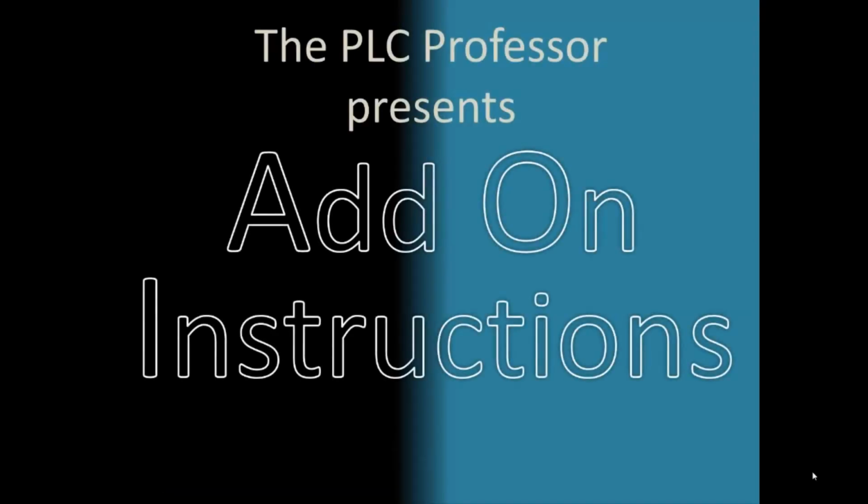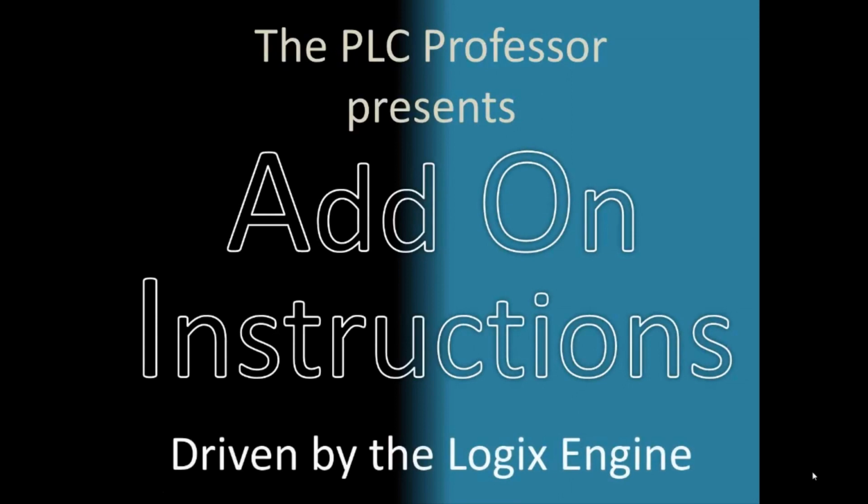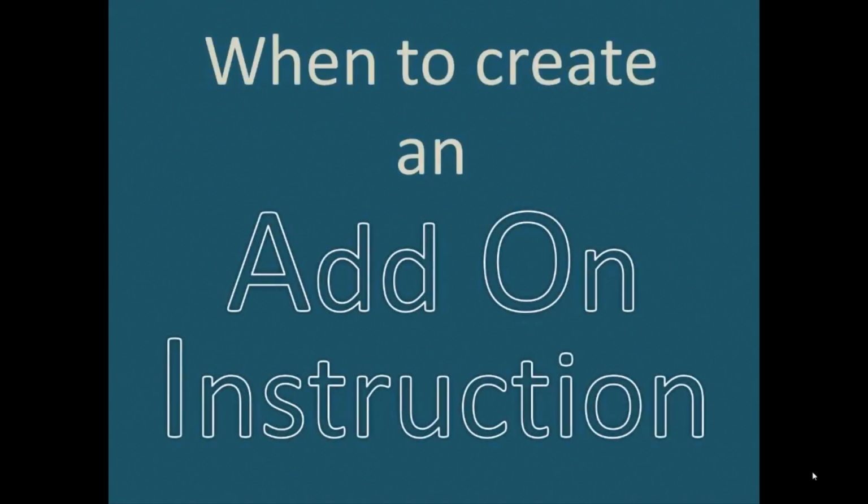The PLC Professor presents add-on instructions driven by the Logix engine. When to use an add-on instruction. When to create one. Complex instructions tend to be highly application specific and not reusable, or require extensive configuration support code.